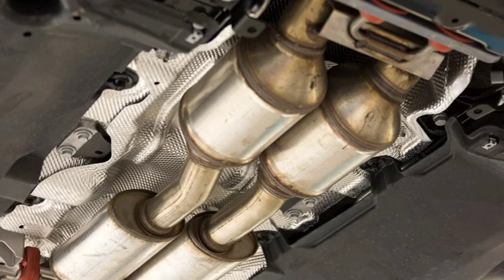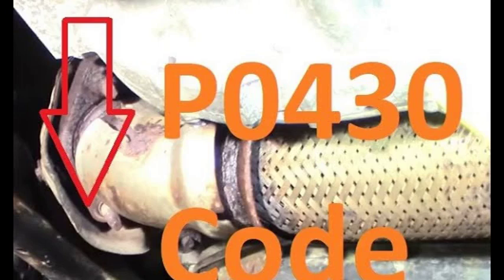Yes, a bad oxygen sensor can cause the P0420 code to be triggered. The oxygen sensor is responsible for monitoring the amount of oxygen in the exhaust gases. If the oxygen sensor is not working properly, it can send false readings to the engine control unit, ECU, which can cause the ECU to set the P0420 code. The P0420 code on a Nissan is the same as the P0420 code on any other vehicle. It indicates that the catalytic converter is not functioning properly.